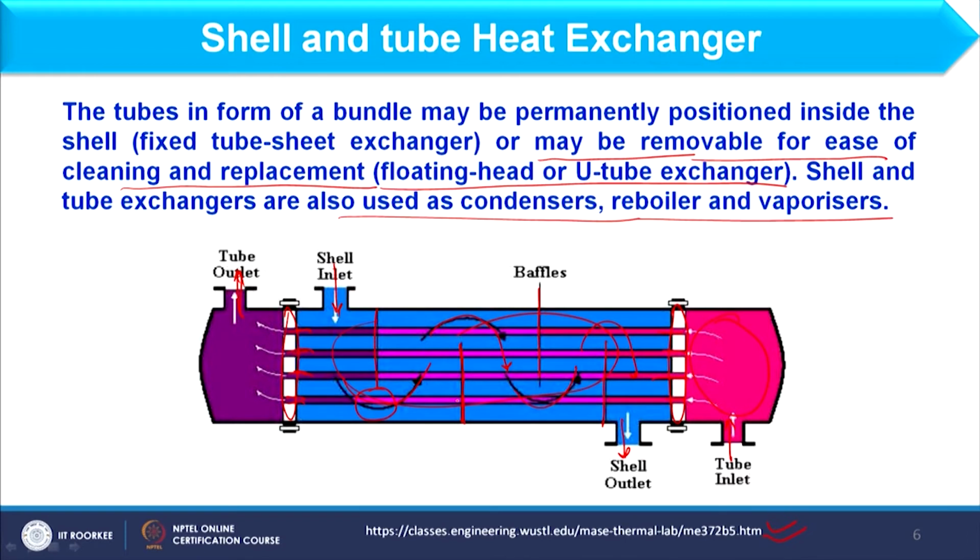Okay. So when I am considering the tube bundle, it basically includes this tube sheet, these tubes, baffles and rods. So where rod is attached like this here. Okay. Rod is attached here. Okay. This rod is not the part of the tube.